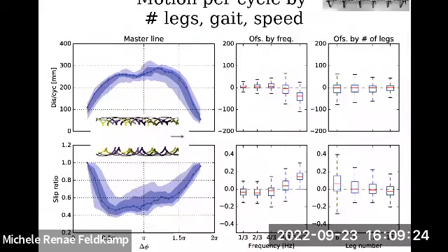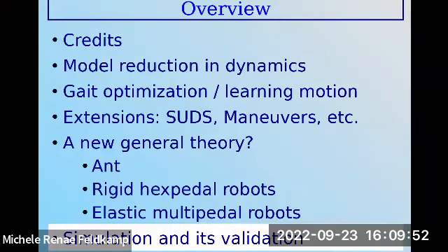How much do the number of legs matter? Almost not at all. So you'd think that a 6-legged robot and a 12-legged robot walking a factor of 10 in terms of speed different from each other would behave differently. It turns out that the 12-legged robot is like 2 6-legged robots walking in a convoy, and you don't even need to know how fast they're moving. So it's vastly simplifying what's going on. Okay. So I'll skip this as well and say the next thing we wanted to do is, okay, this looks really promising. Let's try and simulate this.